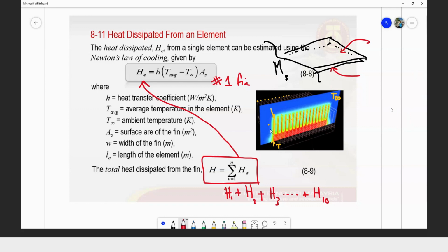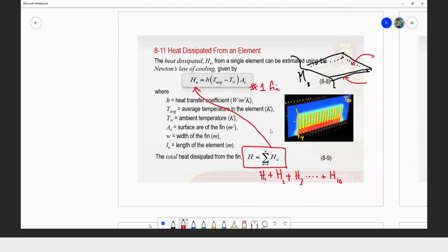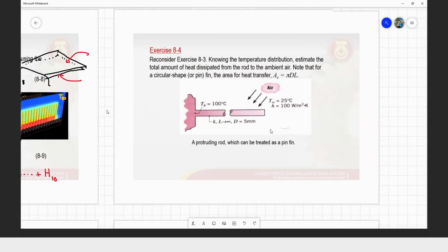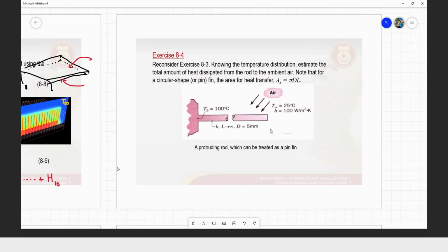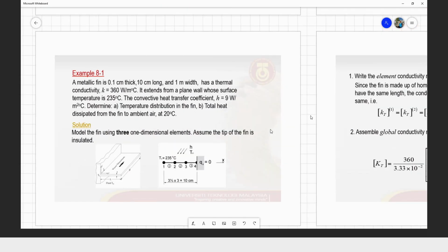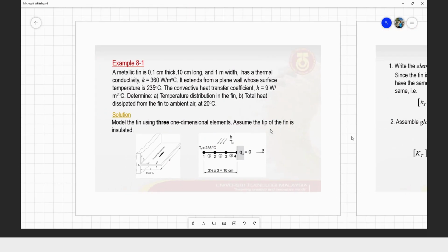But if you use too many, it will cost you in material. The material cost, iron, aluminium, is expensive; you have to buy it, you don't get it for free. So you have to imagine what the optimal number of fins to be used is. It would be good to make this a final exam question: get the optimal number of fins. Alright, I think that's all for thin fins.